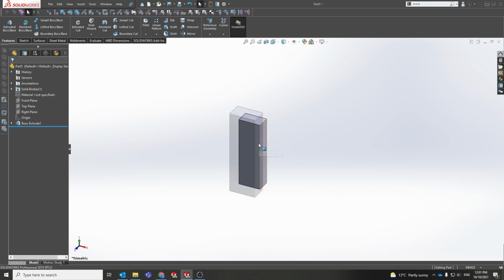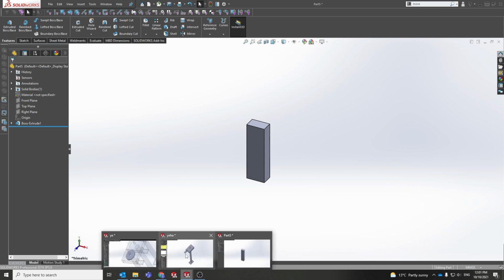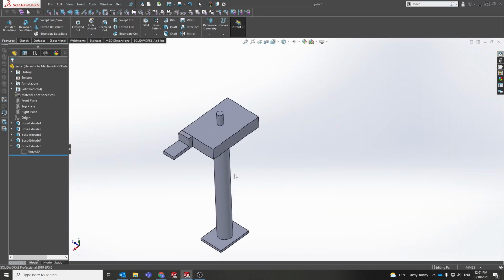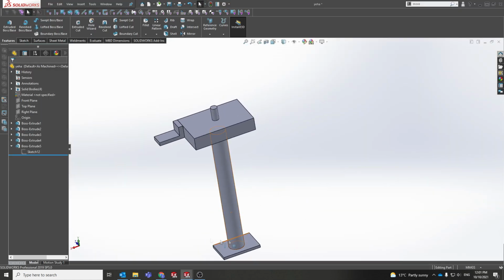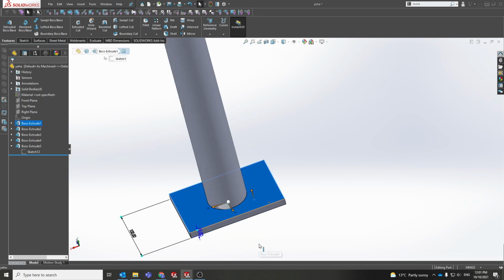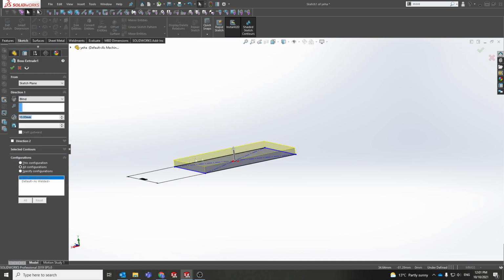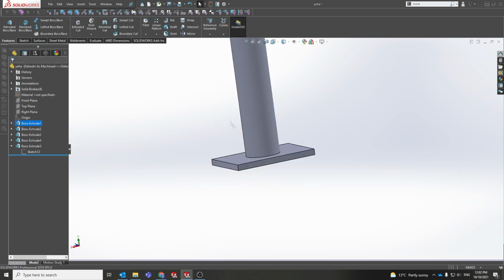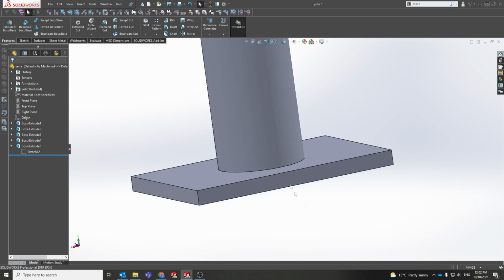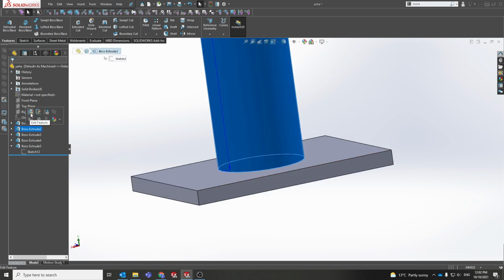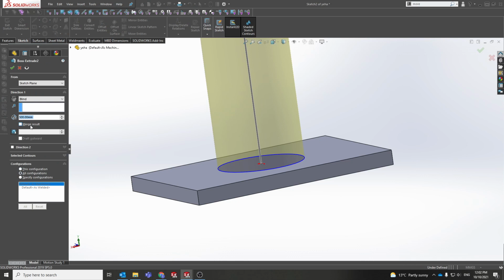And there's also an option to export parts from an assembly. Let's go back to that same little tower thing here. You've built this as a part, so these are all extrusions. I go back into the edit extrusion. They're actually not, that's the wrong one. These aren't actually connected, you see. If I click on this, edit part, I've actually unticked merge result. So if I tick that again, you'll see what I mean.